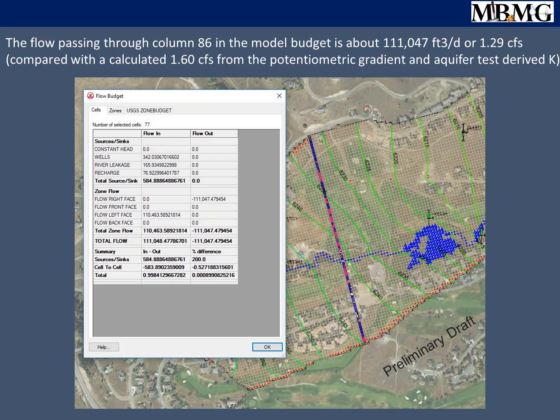I understand now, because that 100 was feet per day, and it's a different parameter. It's not really a flow. It's a property. Whereas here, for comparison, the low flows in the West Fork are about 8 to 12 CFS in the late summer. So 8 to 12 versus 1.5 going through the aquifer. So you have something to compare to.